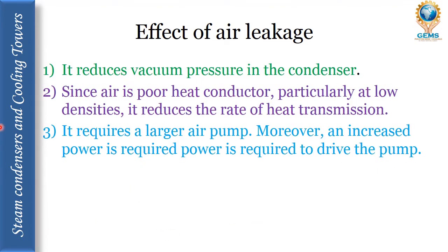So what is the effect on the condenser? Leakage air enters into the condenser, so it reduces the vacuum pressure in the condenser. Since air is a poor heat conductor, particularly at lower densities, it reduces the rate of heat transmission. So if air is entering the condenser, it slowly reduces the rate of heat transmission. So it requires a larger air pump. Moreover, increased power is required to drive the pump.